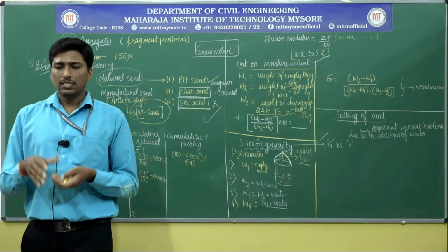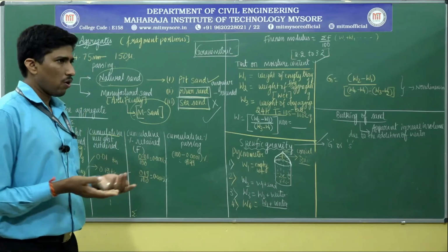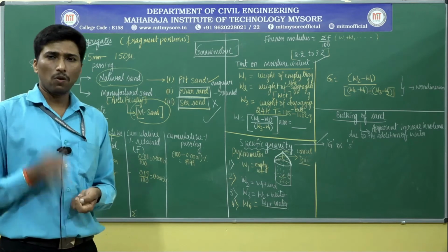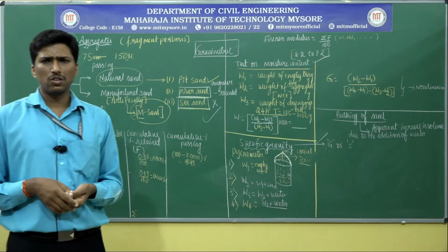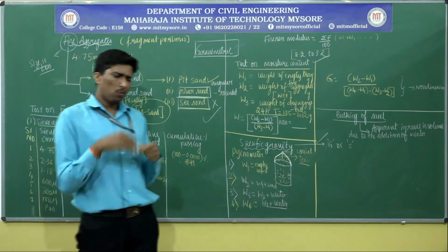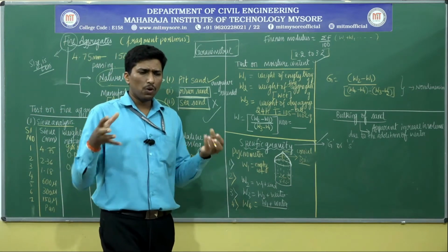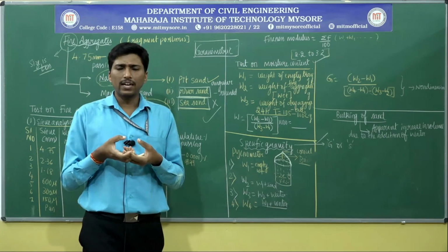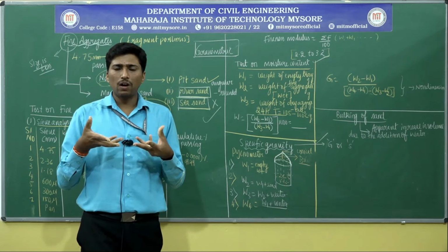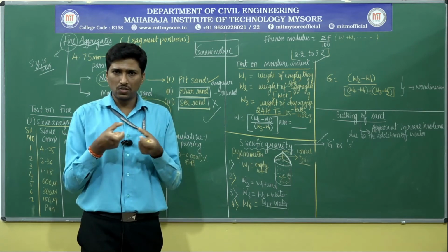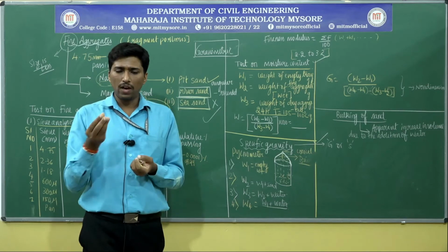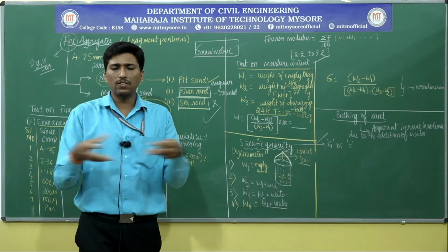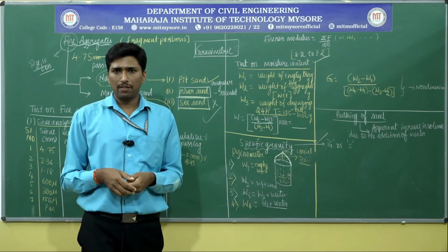But it tends to seem that, oh, a huge amount of sand is present. No, bulking has to be only with respect to the optimal content. What happens if you add more and more water? The particles which have been held together due to surface tension tend to drive away from one another. If you have a small quantity of sand and you use a large amount of water, what happens? Everything is splitting up, isn't it?